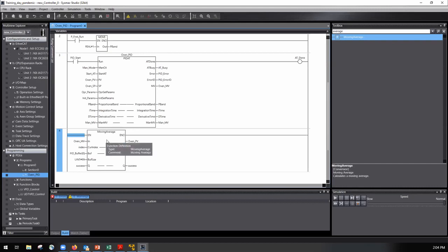With the moving average block, I'm going to slow it down a bit. Even 100 points is done far too quickly in these PLCs. So we have some instructions in Sysmac Studio where we can access time bits. You do it a lot in, like, a CompactLogix or a MicroLogix, sorry, you access the timer bits so you can get seconds, milliseconds, that sort of thing. So in Sysmac, I just type get.